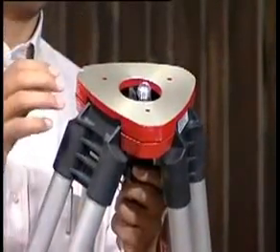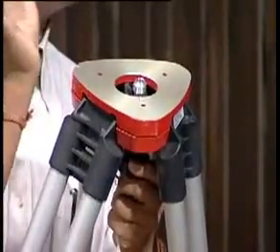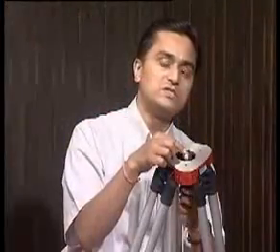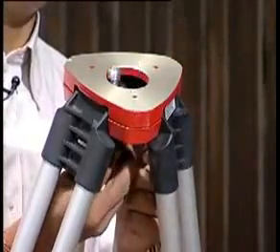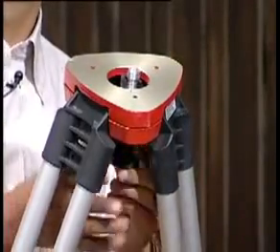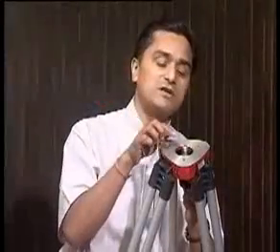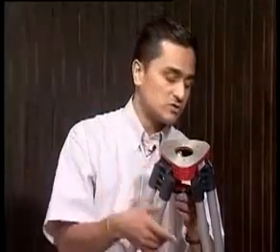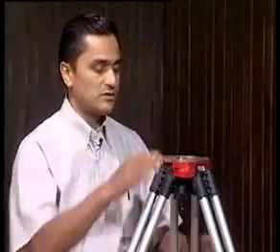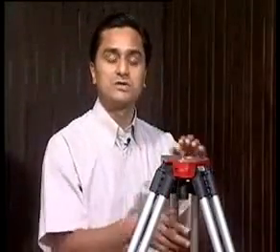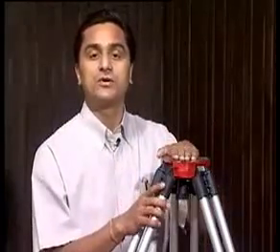Having done that, to do some fine centering of the theodolite, we use this assembly, which is called the centering head. I can move it like this and relax it and move it like this, and that will do my leveling, or sorry, centering very accurately. So this is the centering head. The theodolite is put, just rotation of this, and fine centering is achieved. We'll talk about this again later on.